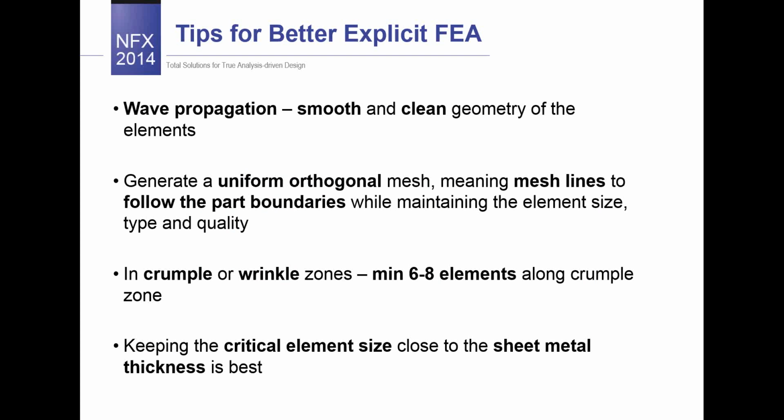Keeping the critical element size close to the sheet metal thickness is also very important, to keep the same proportions of your elements.